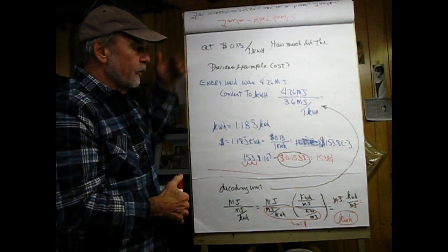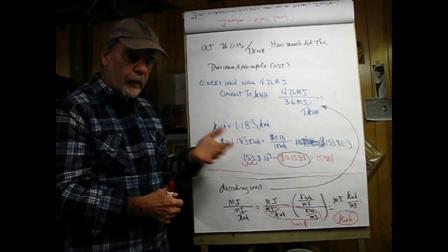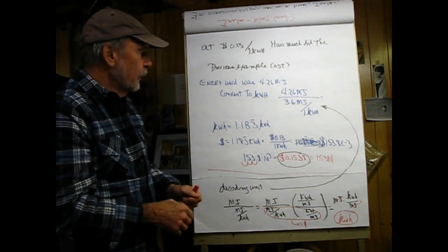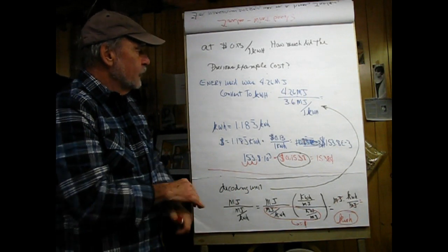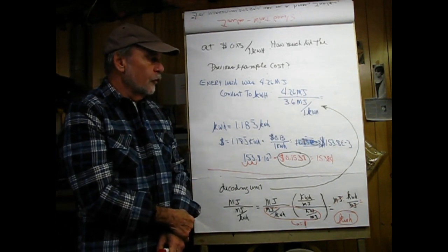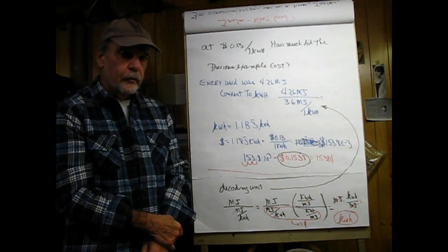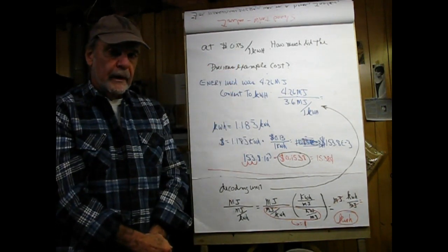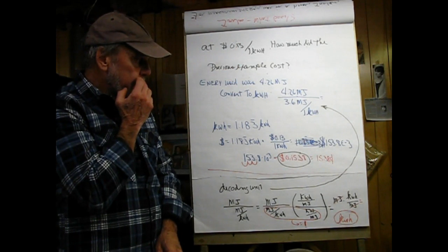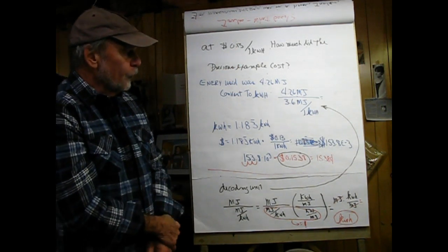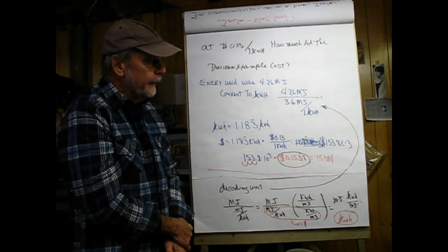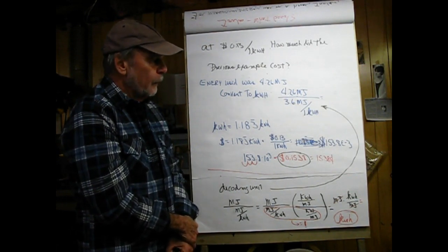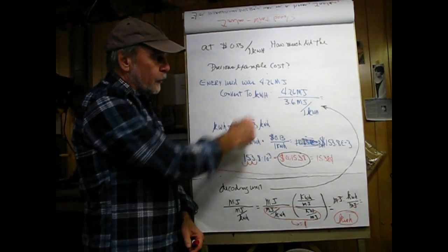What does this previous example cost? How much is it going to cost us to run that toaster and the baseboard heater? So the energy we used was 4.26 megajoules, and what we have to do is convert that to kilowatt hours, and since we know the rate per kilowatt hour, calculating the cost would be straightforward. So first we need to know how many kilowatt hours we used, and I'm going to do this by breaking this down into the joules first.